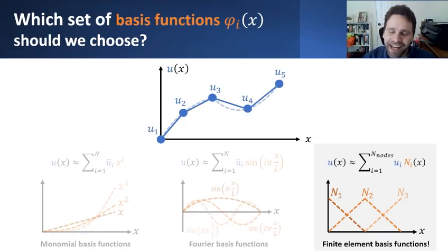And that lack of smoothness could have been a problem if we were considering trying to solve the original strong formulation of the boundary value problem. But thanks to the fact that we've formulated everything in terms of this weak formulation, it's okay if the solution maybe has a derivative that's not particularly well defined at the specific nodal locations. So that's really the workaround that we get from using the weak formulation.